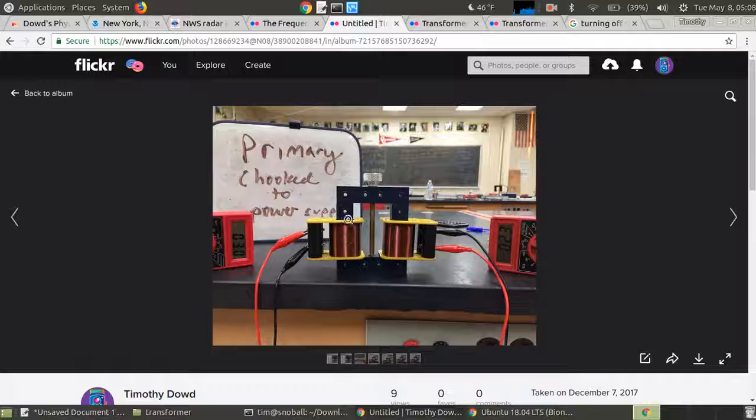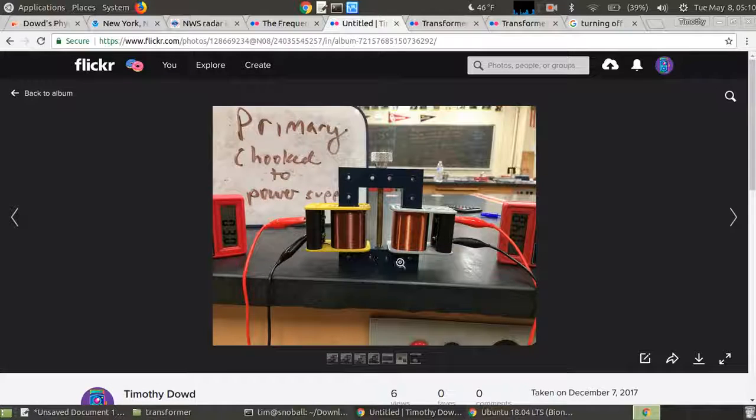So here we have 2 identical coils. They're not connected, so the magnetic flux coming out of this coil is what's causing a voltage in the other coil. Since these are the same coils, we'd expect them to get roughly the same voltage. 3 divided by 400 should be equal to 3 divided by 400. We lose a little bit because the transfer is not 100% efficient here. We still have a primary voltage of 3 here, but we have 800 turns or twice as much over here. So if you solve that transformer equation, you should get twice as much voltage, or 6. You can see we're roughly in that ballpark. Again, there are some losses.